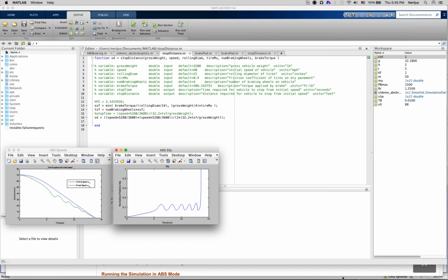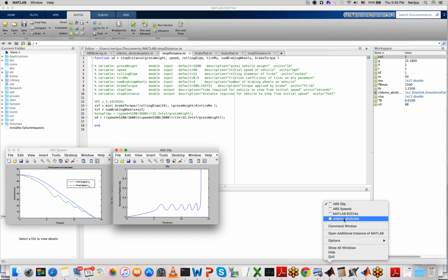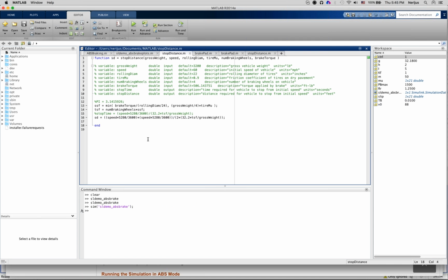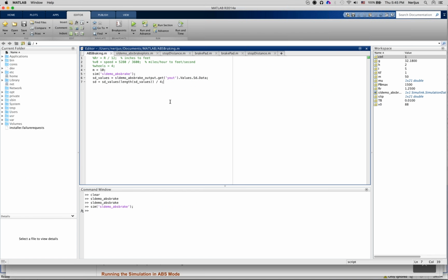Even if you look at the model itself, it has stopping distance here as one of the outputs of the simulation. So actually it writes all those simulation values into the output file, into the results file. And so I should find this file and take the values I need. So I used a very small script for that, in which I can set some initial values like initial speed, how many wheels I have, or diameter and mass, and then actually read the file, whose name I found in the help.